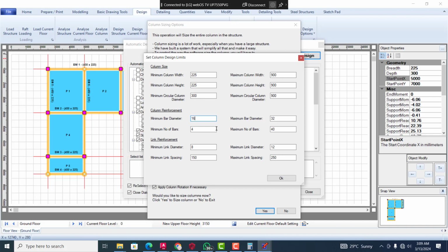Some people use Y12, but like we know, when you want to buy your reinforcement, if you use the vernier caliper to check the diameter, it doesn't usually even reach. Most times in your design, the design may tell you to use Y12, but it's customary to use Y16 because of that Y12 availability.